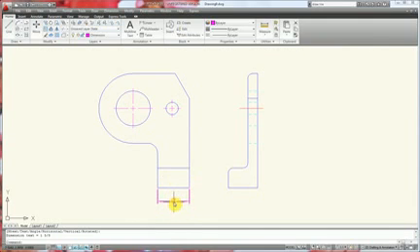So I'm just going to simply press the space bar to re-enter the linear dimension, and I'm going to dimension the rest of this. Be careful that when you have dimensions that have these offset lines at the same point, you don't actually snap to that line. The way you can tell here is, say I accidentally snap to that line in the center point, I'll get a really funky dimension. So we're going to undo here, press the linear dimension, and make sure I'm actually snapping to that corner point. Now I have a more standard dimension.